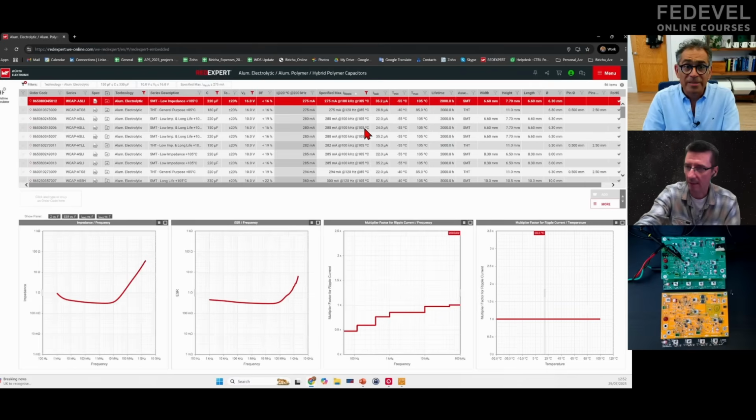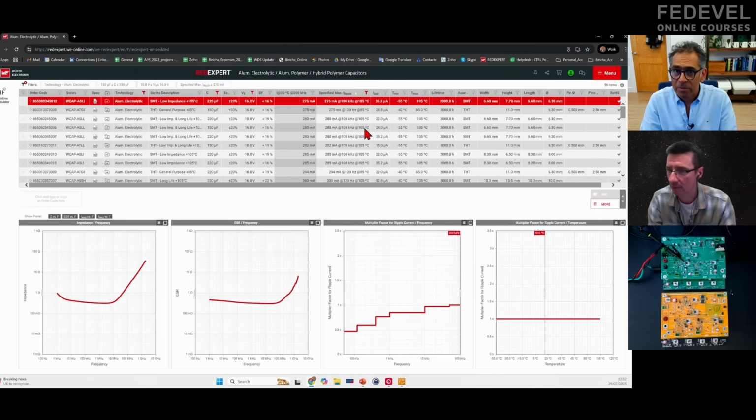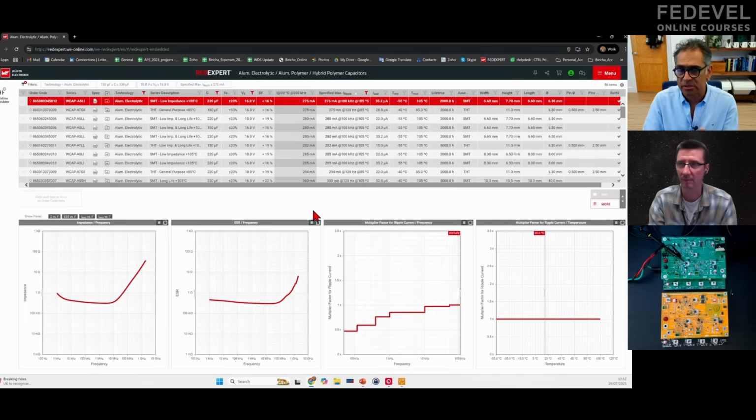So do you select some kind of frequency there, or? Finally, yes. So the ripple current rating goes up with frequency, right? You're very observant, and you notice this graph here. Yes. So it goes up with frequency, right? And therefore, this tool provides you with a multiplier, right? To allow you to calculate it exactly at the correct frequency. And of course, our frequency is 200 kilohertz, right?